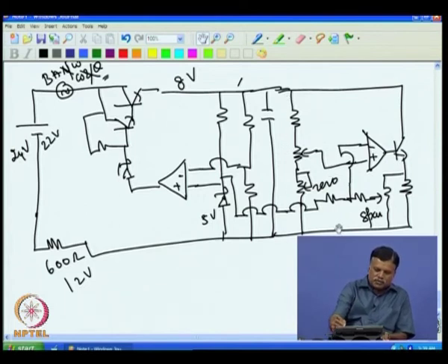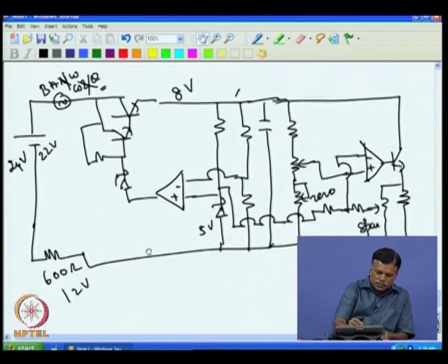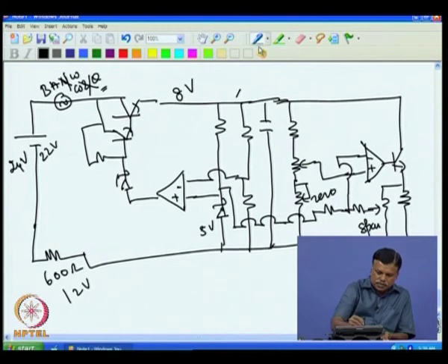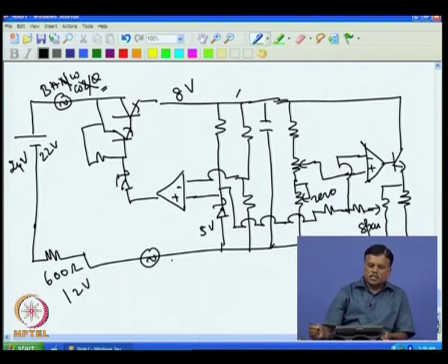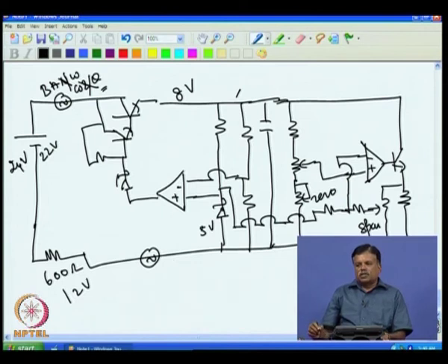Of course, you may have noise voltage induced in this part of the loop, for example here. Now, this also has to drive the current like this only, but then we know that as long as this voltage is not changing, this current also will not be changing. So, external noise will have no effect on the current. That is why this current transmitter is used, and also only 2 wires are used.